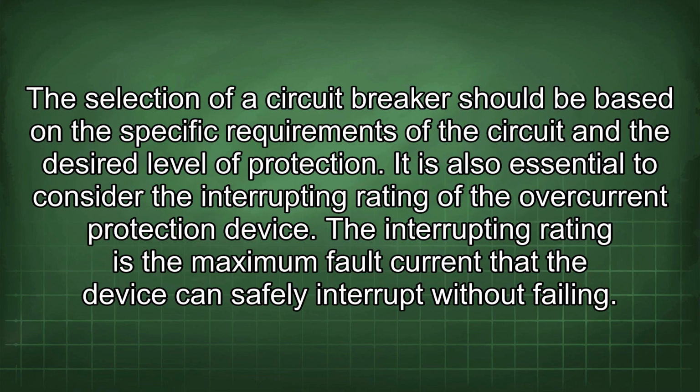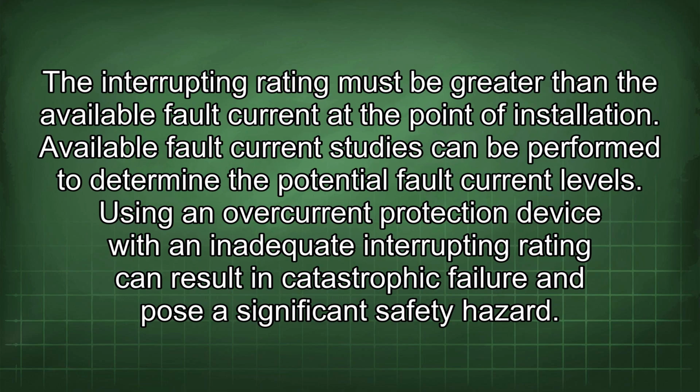The selection of a circuit breaker should be based on the specific requirements of the circuit and the desired level of protection. It is also essential to consider the interrupting rating of the overcurrent protection device. The interrupting rating is the maximum fault current that the device can safely interrupt without failing. The interrupting rating must be greater than the available fault current at the point of installation.